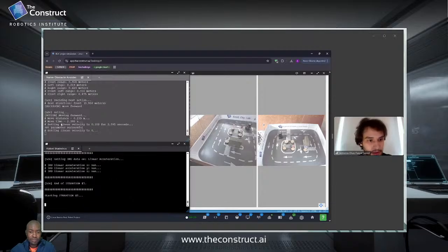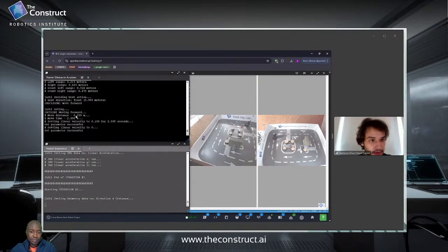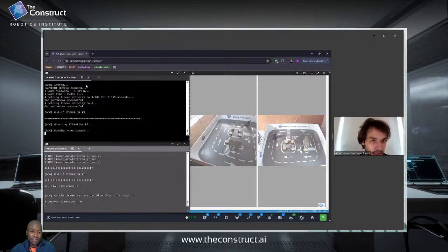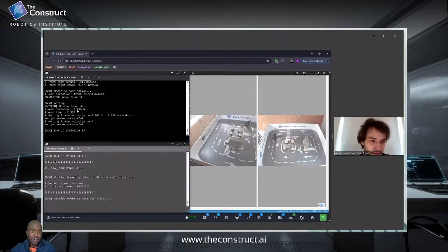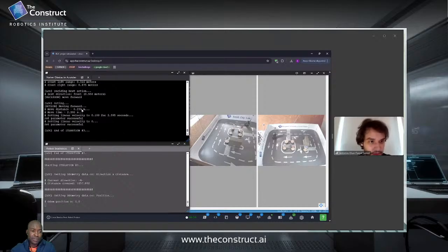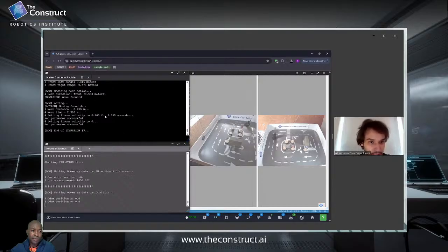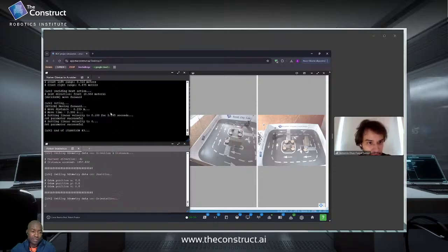You may see here on the log, it says it's approximately 1 meter and then it runs for approximately 0.25 meters. Then it sets that velocity based on a simple operation of division. For that amount of time, it sets parameters, sleeps for this amount of time, and then sets back linear velocity to 0. All right, I see.